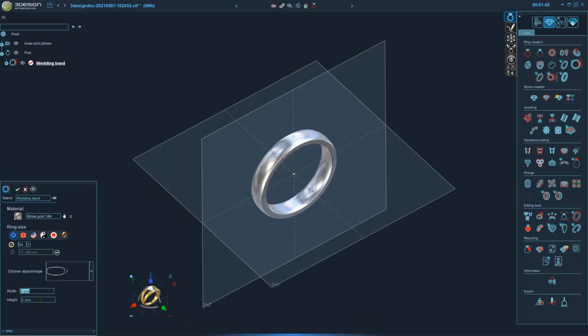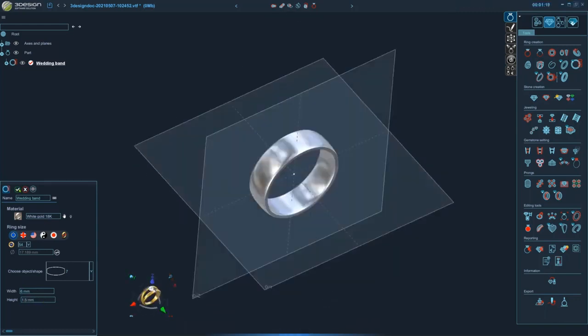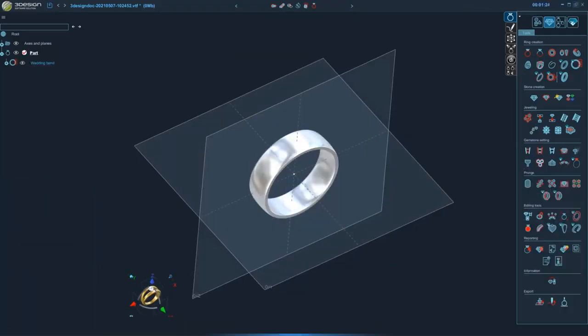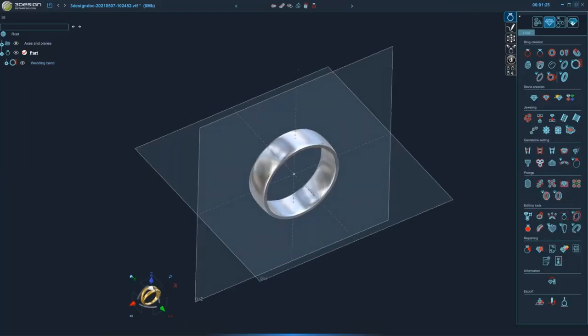There is a width and a height. It's not done using the manipulator because it's using the sweeping functions. So you will type those in, but if I want a 6mm wide band, that updates. And if I want it to be 1.5 thickness, and again, just a few clicks, we can create those really mundane things that we do over and over with just one simple tool.